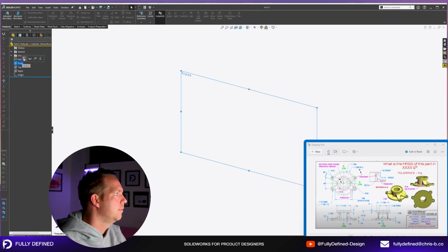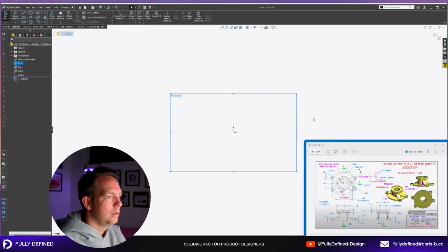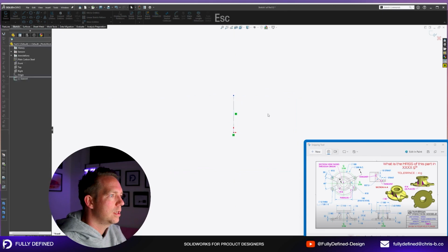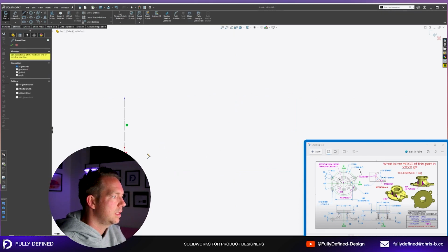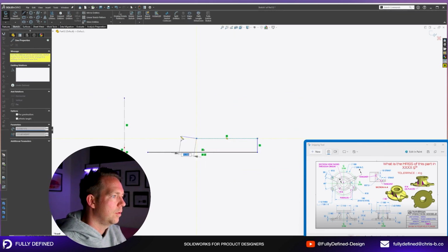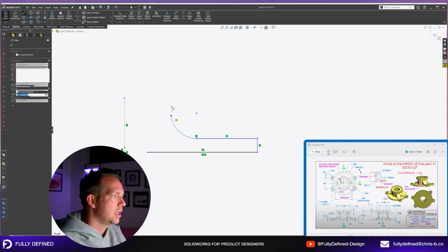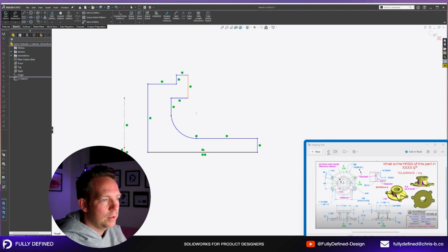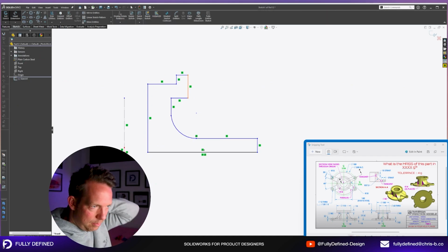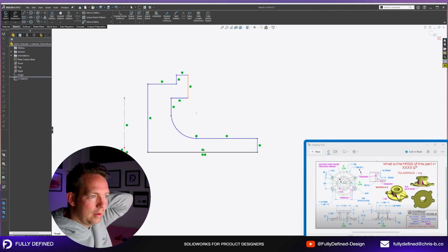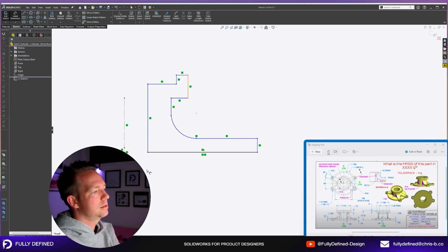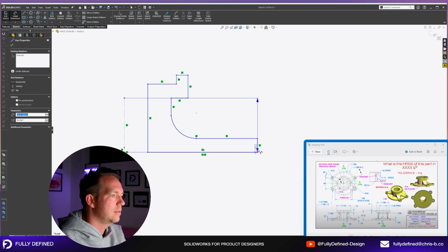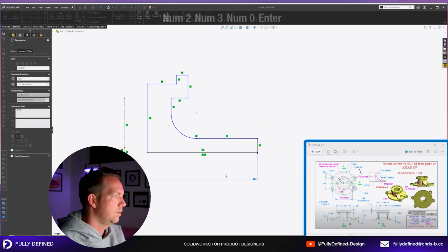Let's do it. All right, I'm starting with the section view, and I'm just getting a construction line in there and then going to sketch this profile down the bottom. Not worrying about dimensions yet. I'm just getting the shape right. I'll come back for dimensions later. Now I'm using the 200mm circle on the outside plus the 30mm diameter for those arcs, 15mm radius. That's going to give me my full width, 230.